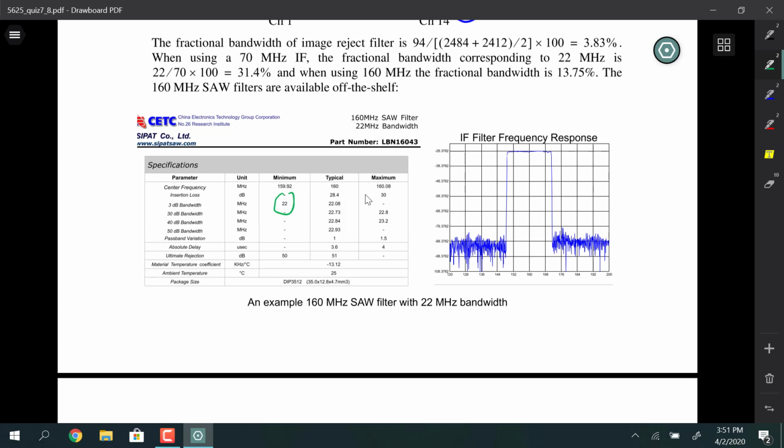It could be a Hanning or Hamming or something like that. I don't really remember the intimate details, but it's an analog version of an FIR filter in a sense, based on these interdigitated structures. And maybe, John, you know more about this because you've probably bought these before or spec'd them before for a design.